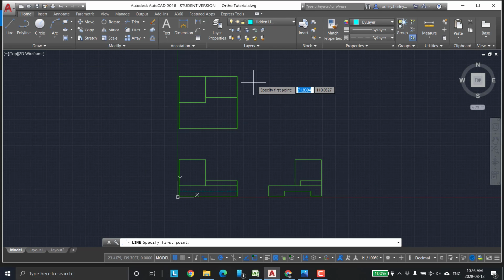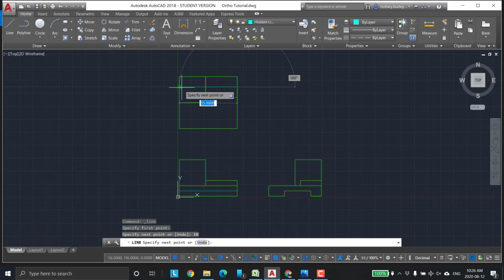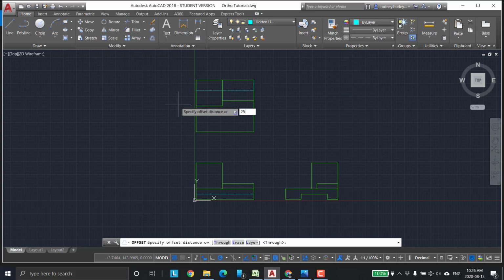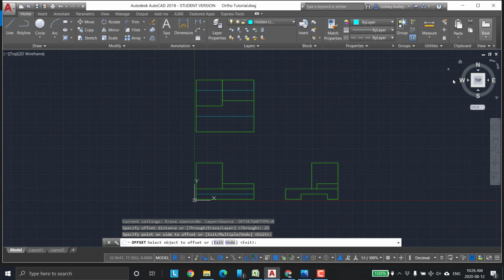The first one would be, click on this, you come down this way, it's 10 millimeters. So we're locked in at 10, we run across this way and bang. So we've got that. So now this line right here is that one running across. The next one is parallel to this, running 25 millimeters down. And there's several ways we can do that. We can click this line here, and then we could click on offset, and we could say offset by 25 millimeters, enter, and which side, and we could do it that way.